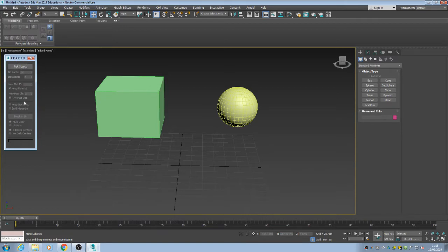With many of these scripts that you can find, some will work, some won't work, some can be a bit buggy, but usually they'll have a menu or some function that you can use to control your objects. So I'm going to select my box. I'm going to say pick object, so pick current object I want to fracture. So you see it says Box001. I'm not going to worry about the ID channels for now. It's going to ask me how many parts I want to break it into. We can say iterations. You see it's going to break into 100 pieces. We can put this down to 5, so we're going to break into 25 pieces for now.